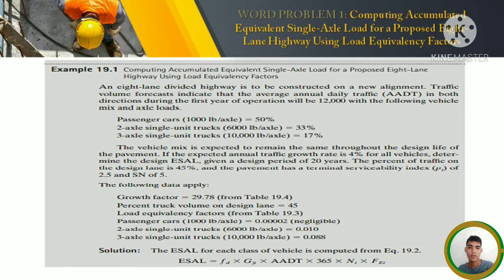So the solution: we're going to use the equation for the ESAL. The general equation is ESAL is equal to F sub D, or the design lane factor, times the G sub R of n times AADT times 365 times N sub i times F E i.